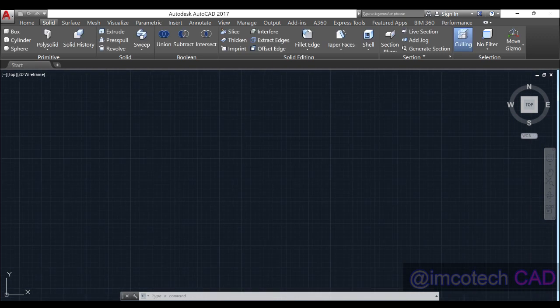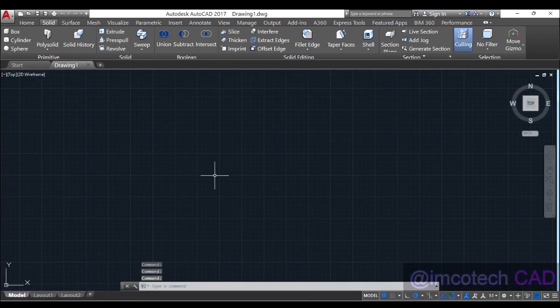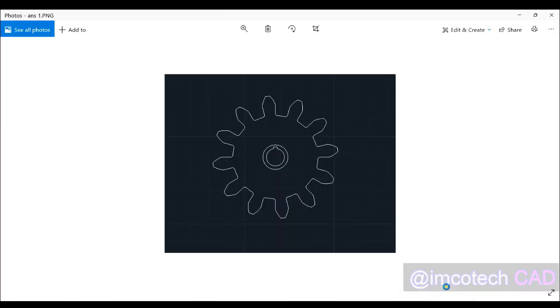First and foremost, we need to know 4 basic parameters of a gear. So I'm going to show what I've plotted earlier. I want you to see this first. This circle you are seeing here is called the dedendum circle diameter, and the top circle you are seeing here is called the addendum circle diameter. And along this place, where these arcs were made, from this point to this point to this point, is called the pitch circle diameter. And there will be a circle below it called the base circle, used to cut those arcs.